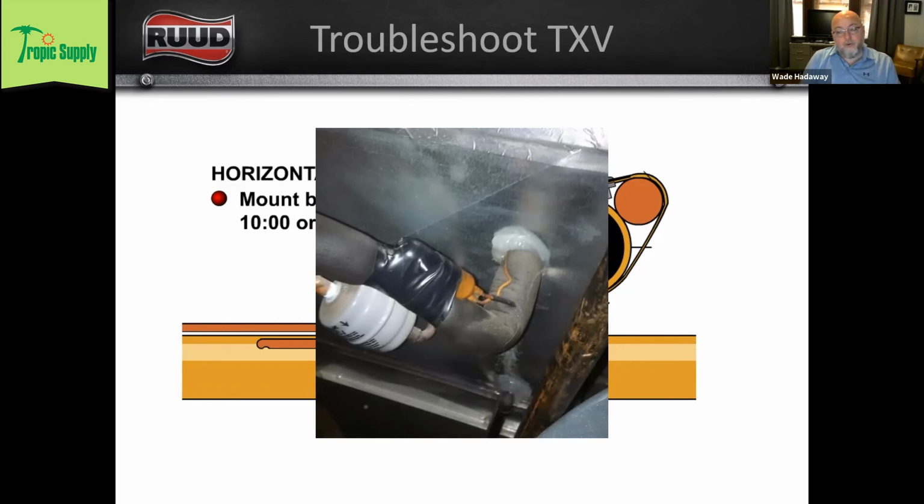If you look at line sizing charts, you might use 3 or 4 different sizes of suction line or liquid line that would be acceptable. And if you did that, you'd have to have a different bulb with a different sort of concave shape for each line set to really get a good connection there. That's my assumption.